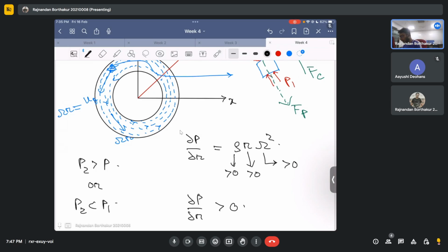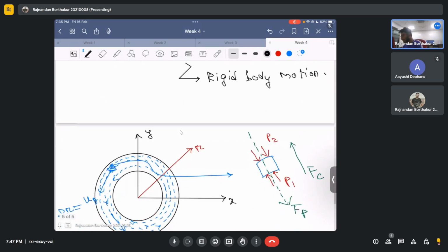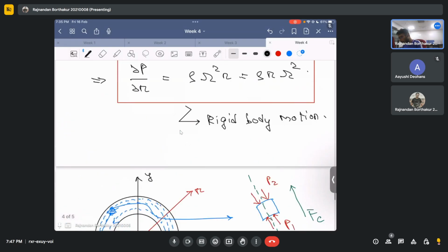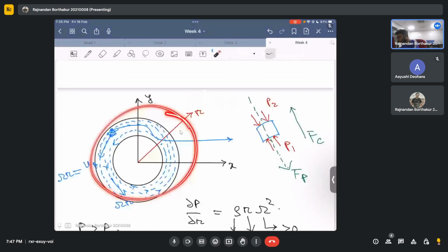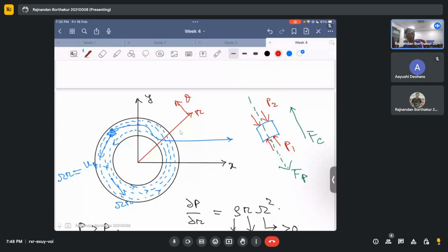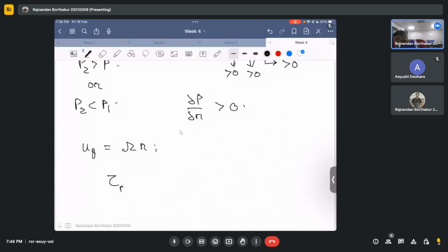All right. So if you don't have any doubts, let's do one thing. The velocity profile that we got for this case is u theta equals omega r, as you have rightly pointed out. Since this is the r theta plane that we saw, where the theta direction would basically be something like this, when, of course, r changes, the direction of theta coordinate also changes. So let us evaluate the viscous stress tau r theta in this case.